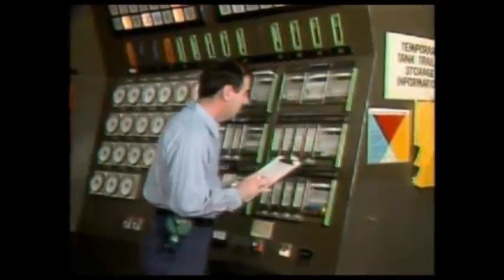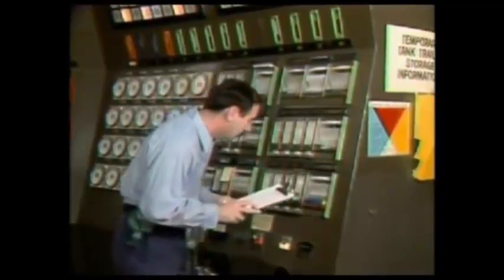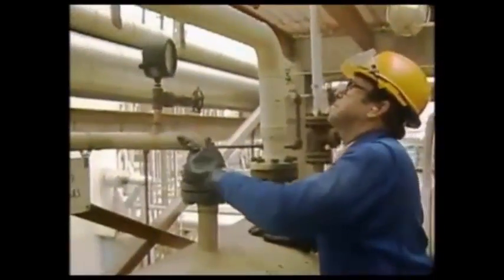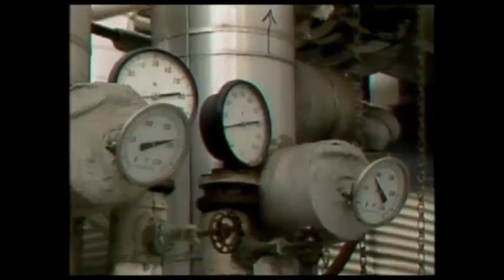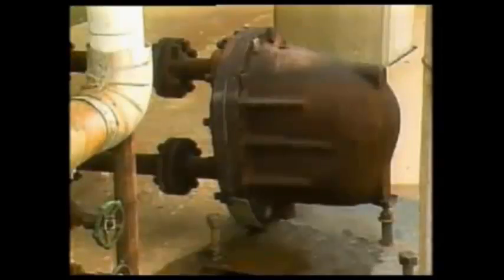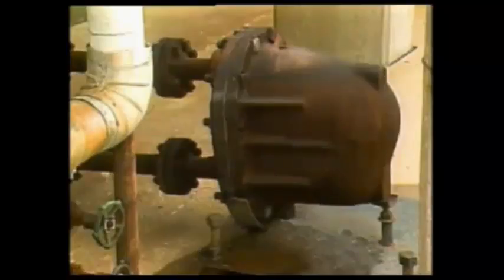Generally, an operator can observe instruments to determine if a heat exchanger is operating properly. These instruments are often located in the control room, but they may also be found on or near the heat exchanger. Depending on the heat exchanger and its use, pressure and temperature gauges may be placed on any or all of the heat exchanger's inlets and outlets. On heat exchangers that use steam, an auxiliary device called a steam trap is often used. The steam trap drains water or condensate from the steam in the heat exchanger without letting the steam escape. Lost steam reduces the efficiency of the heat exchanger.